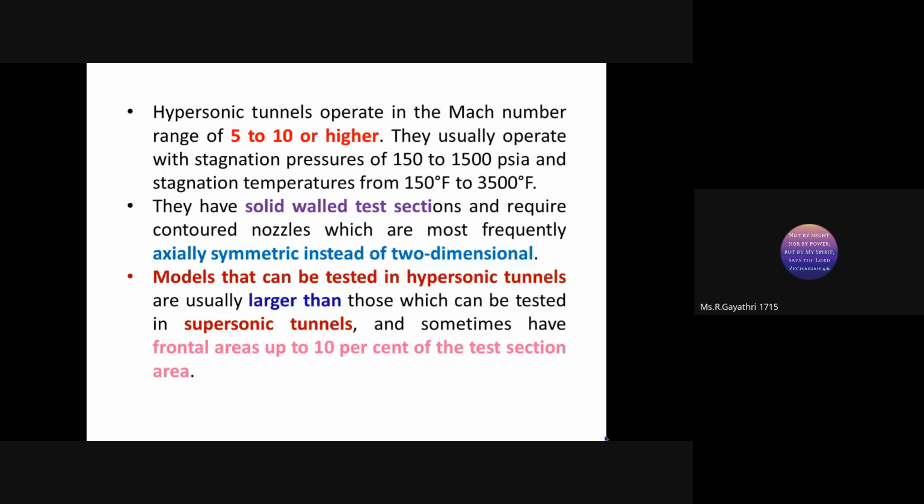Okay, for a supersonic case, we can use scale down model. Here also scale down model is used, but the frontal area of the scale down model is a maximum of 10% of the test section area. We can keep it lower than this also.